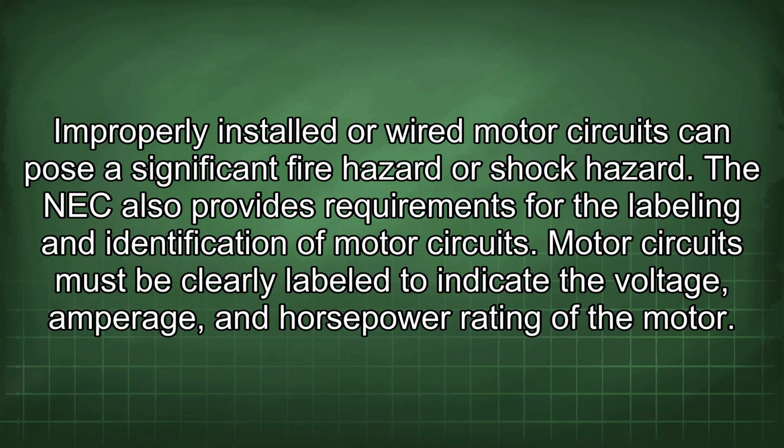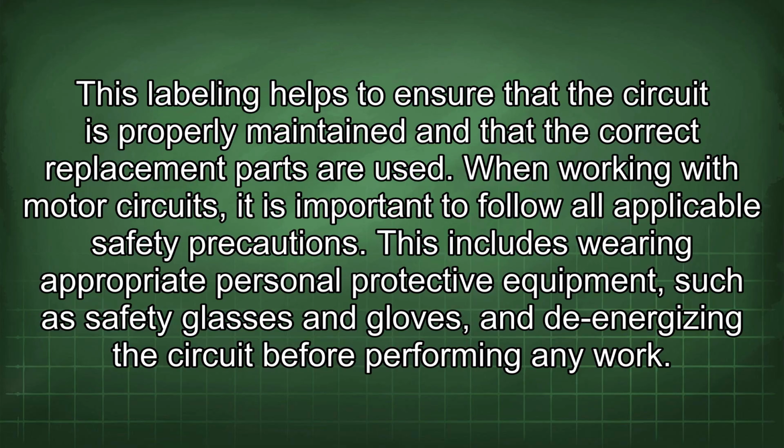The NEC also provides requirements for the labeling and identification of motor circuits. Motor circuits must be clearly labeled to indicate the voltage, amperage, and horsepower rating of the motor. This labeling helps to ensure that the circuit is properly maintained and that the correct replacement parts are used.